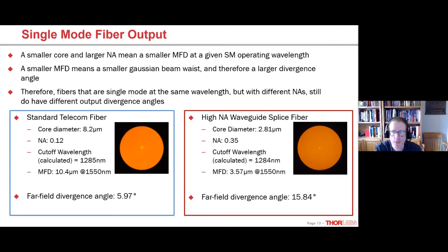Okay, so would the bending of the optical fiber while setting a system up decrease the coupling efficiency? Yeah, so that's something that I think we covered in part one of this webinar. Single mode fiber, one of its virtues is that the fundamental mode is very bend insensitive. So it doesn't really care if the waveguide is bent or if it's straight. There are some limits to that if you really bend the fiber a lot, or there are some subtle effects, but by and large, that fundamental mode propagates through the fiber, and it's not influenced by bending the fiber.